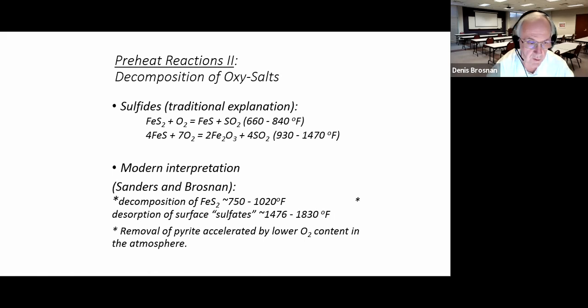Iron sulfide can cause problems. If you have iron sulfide in the clay, you probably know it because you're going to smell the SO2 that's created in burning out the iron sulfide. You'll smell it. There's a bitter smell to this. And if you walk across the top of a kiln and iron sulfide's inside the kiln, you actually will get a taste in your mouth. You might know it from corrosion on the fill stack of the dryer stack because it forms sulfuric acid in the dryer.